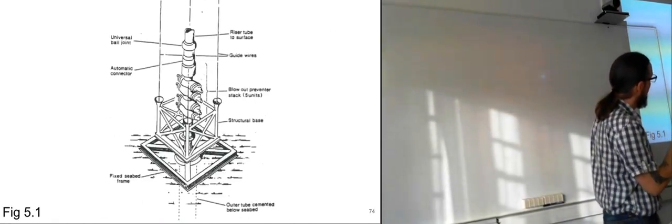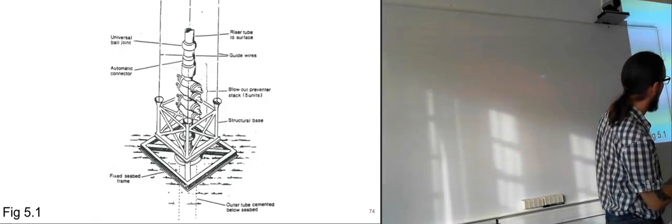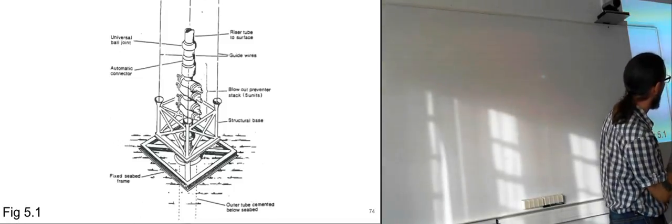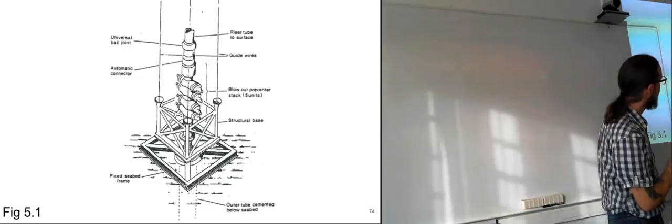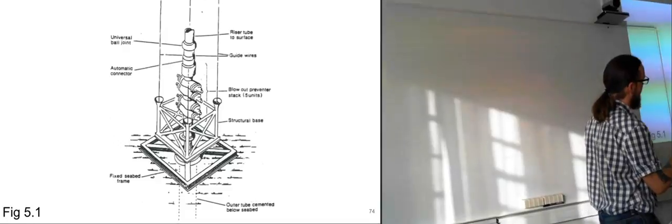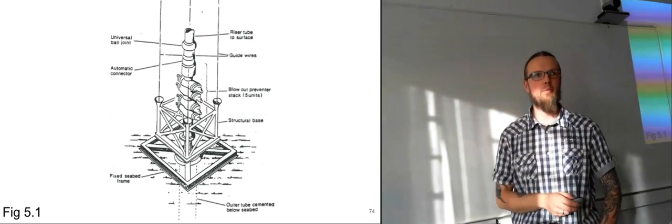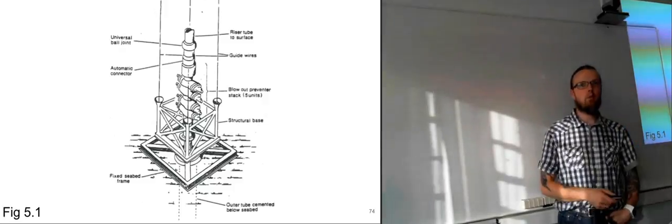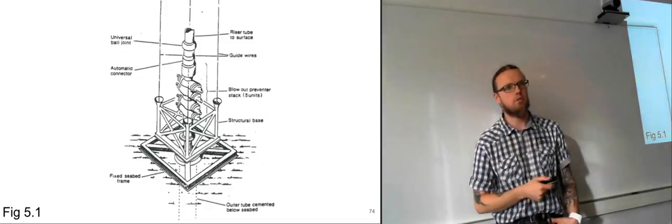So with the guidelines, as you can see with this one, the guideposts are hidden inside on this one. Usually, if you want a better view of it, the guideposts protrude out of the module so that you can actually reach the top and release the guidelines afterwards with the ROV. There might be some sort of release at the bottom here, which we can't see in this illustration.